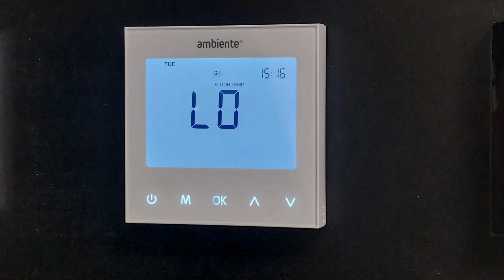If your LunaTouch displays the low error code, the measured room temperature has fallen to 0 degrees Celsius or below. First, check for any drafts or external cooling sources that may be affecting the thermostat. Try moving the thermostat to a warmer location and start heating to raise the room temperature. If the issue persists, check the LunaTouch temperature calibration in the optional features and adjust if needed.